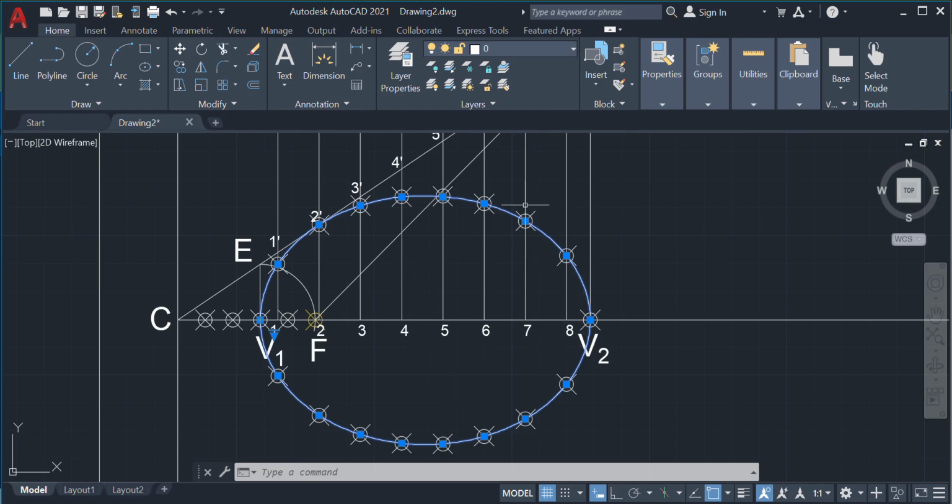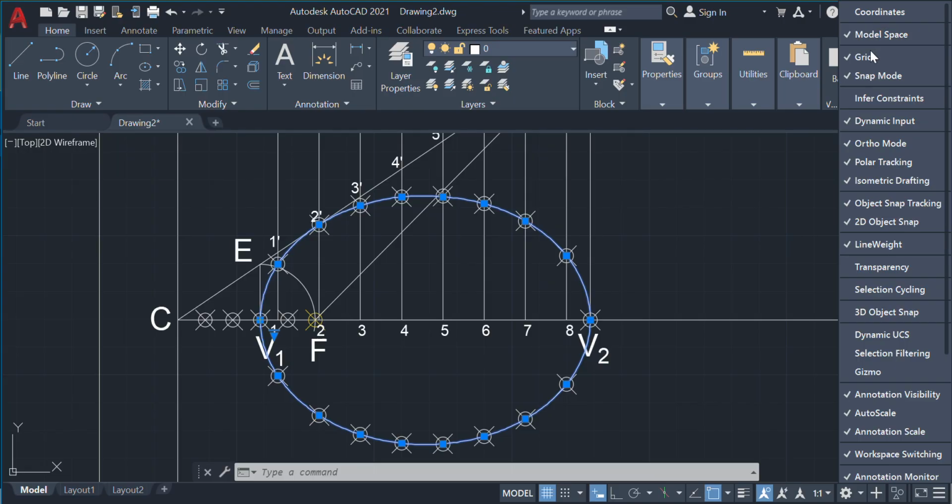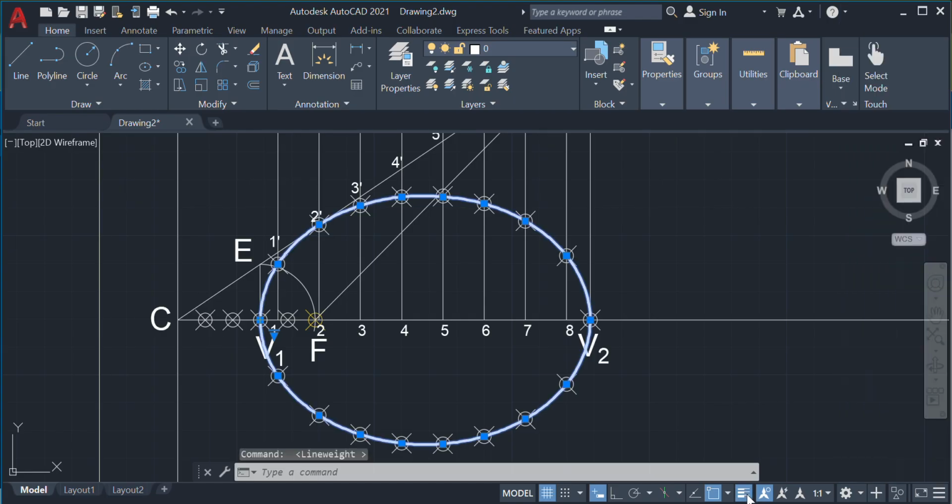So to enable it, you can see we have three options. This is called my customization one. Click on this customization, and you should see there are various options. In that, your line weight option should be on, ticked. When this is ticked, you will see this kind of option will come. By default, mine is ticked. Now I will go to this option and make it on. You can see there's an escape button. You can see it got darkened.